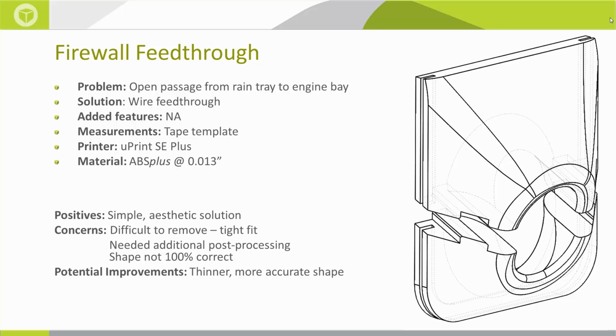Positives on this, it was a simple aesthetic solution. It worked. The concerns, it was a tight fit. I actually had to use a hammer to press it into place or tap it into place. These parts, because they were so coarsely printed, they did need additional post-processing. And the shape wasn't 100% correct. So my tape template wasn't done as well as I could have done, and so it's going to require either I reprint the part or I adjust it with a Dremel.